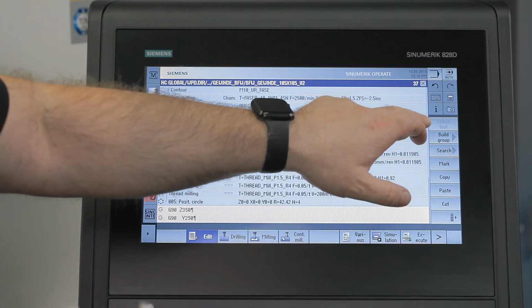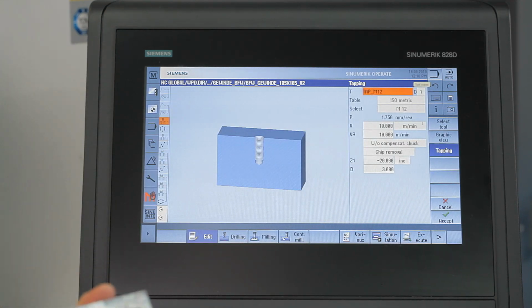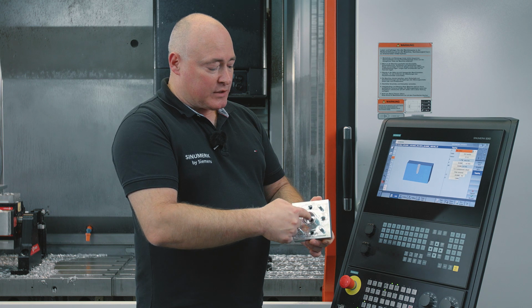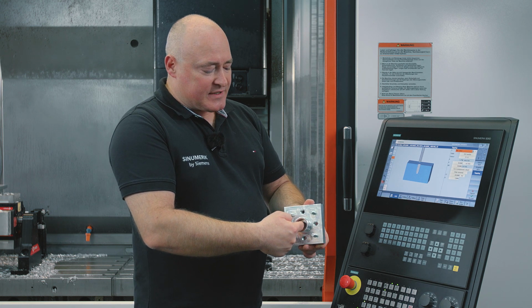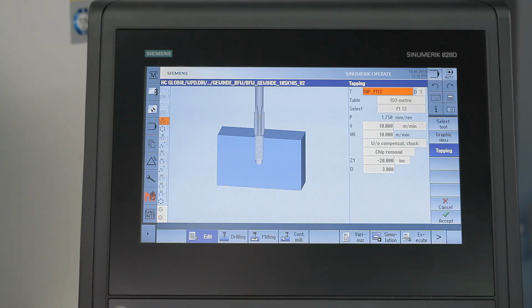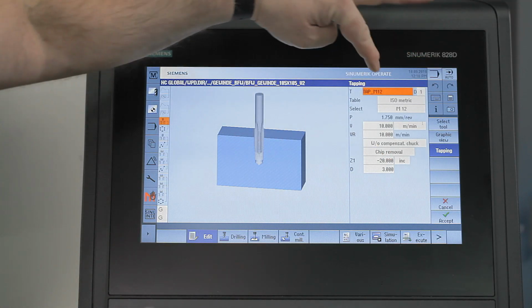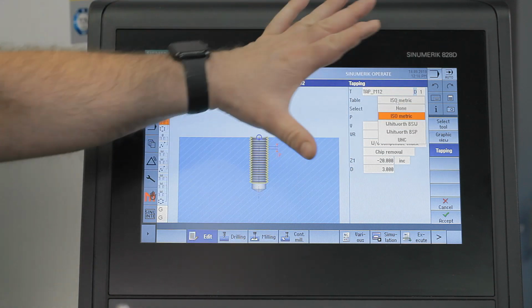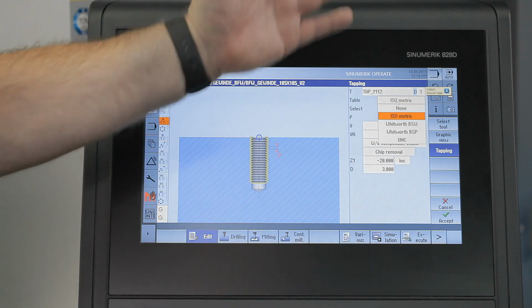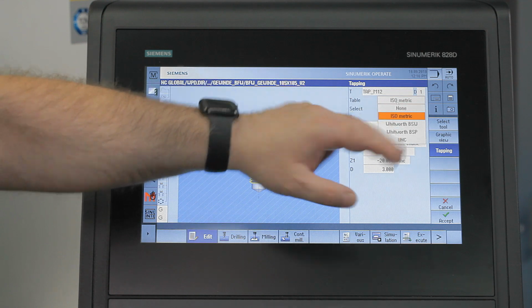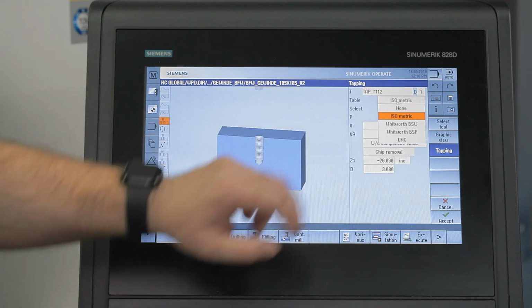The next step is tapping. The M12 tapping in our pre-drilled tap hole diameter, once here in the middle of the M32 by 1.5 and the 4 holes arranged in the circle. After selecting our tool in the tool menu, here we set the thread which we would like to produce, in this case an isometric thread. Alternatively, we can of course also opt for the Whitworth pipe thread, UNC thread.